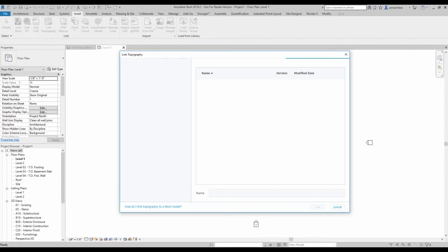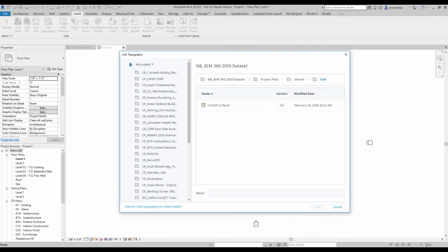So even though when she was running that tool, it gave her the opportunity to save it somewhere on her computer. We use the desktop connector that essentially maps a drive of BIM 360 locally. But this only shows me content that I have access to in the cloud. So I don't have the ability to grab a file that happens to be local or not on BIM 360. So in this case, I can see my file. Let me actually just refresh that folder. There we go. Now I see version 2.